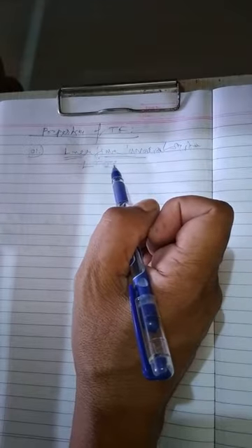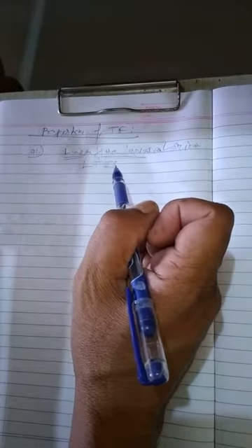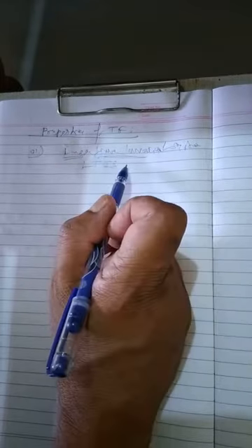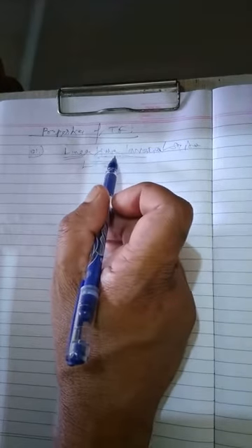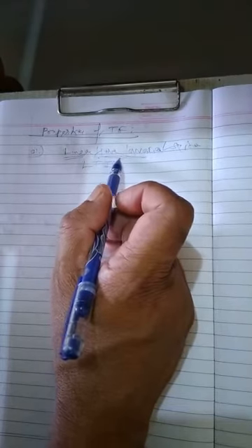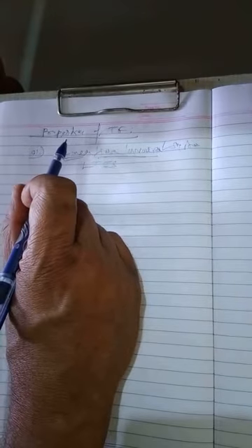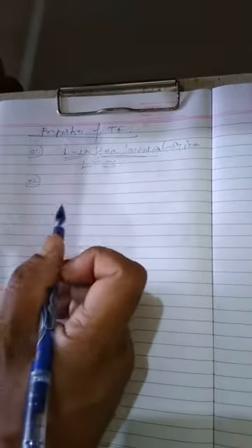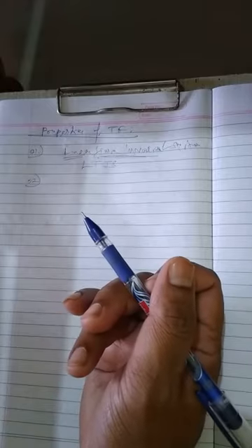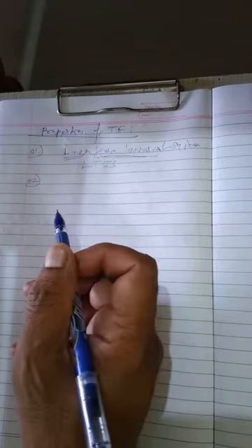So what is a linear time invariant system? Linear systems are those systems whose input-output characteristics are linear. Time invariant means when we change the input signal by some factor plus minus k, then the output is also changed by the same factor plus minus k. Such a system is called time invariant. So transfer function is defined only for linear time invariant systems. If there is a non-linear system, the transfer function will fail for that system.